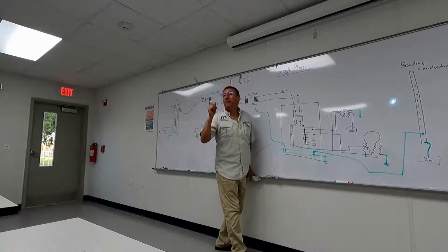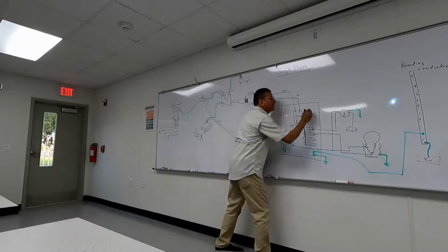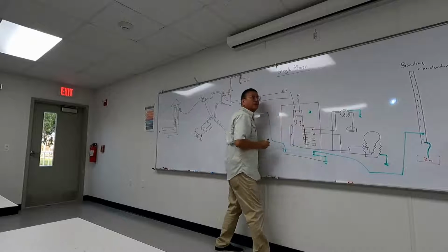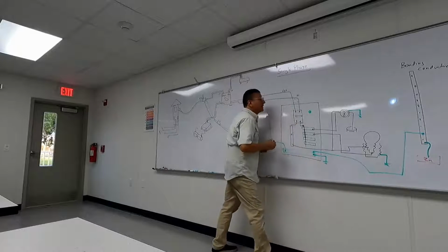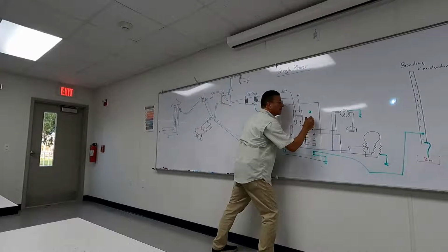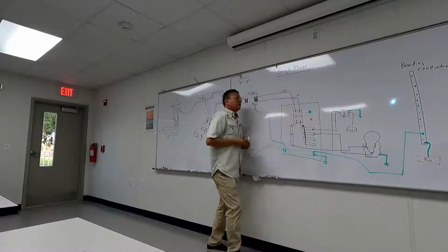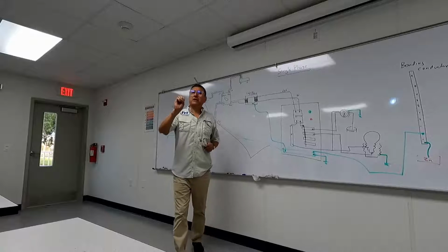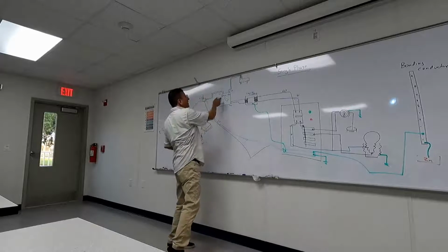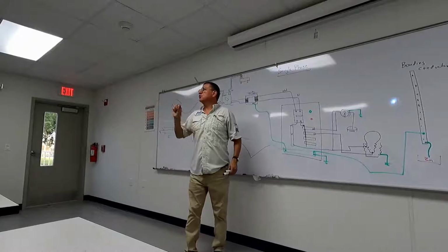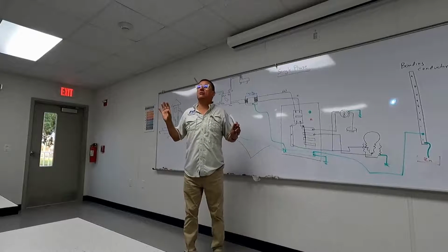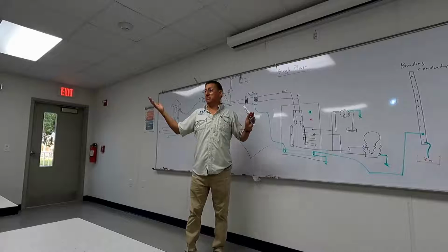if the panel is single phase, you have two LEDs: one green and one red. The green, when the shore power is connected and the switch selector is in shore power, should be on, indicating that you have power coming in.